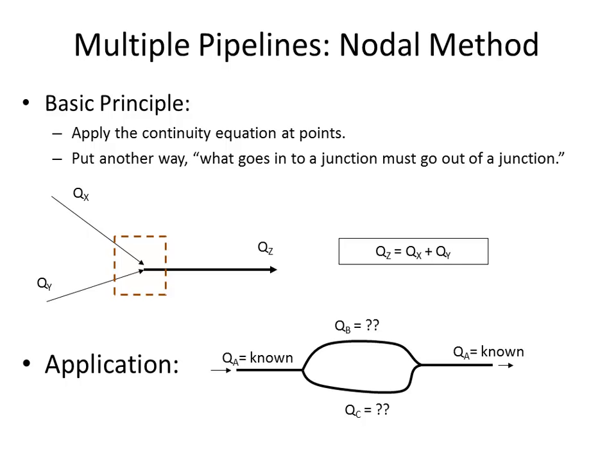But we know that when that pipeline joins together again, if there haven't been any side laterals taking water off, if it's still fully enclosed and there are no reservoirs that allow for accumulation or depletion, no storage opportunities, then the flow rate, once they come back together, is that same known flow rate as went into the junction. So how much will go through the upper and the lower pipes is what we're after.